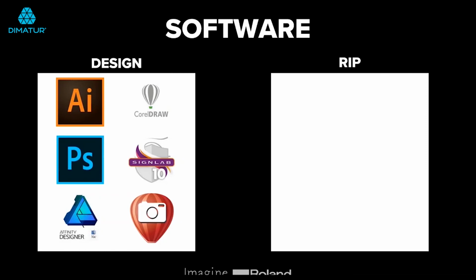The other category that design programs fall into really broadly is bitmap-based programs and vector-based programs. And that's the difference really between Illustrator and Photoshop. To get the most out of your printer and in order to be able to design cut lines, you need a vector-based platform. Fundamentally, the difference between bitmap and vector is that bitmap is made up from a series of pixels, whereas vector are shapes that are concocted from points in a digital space that are joined by lines.